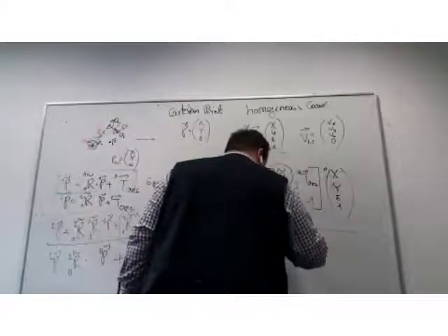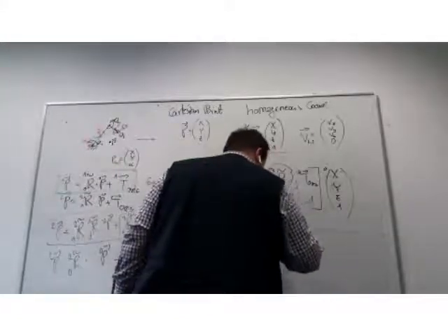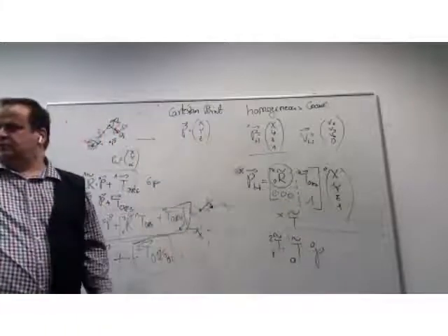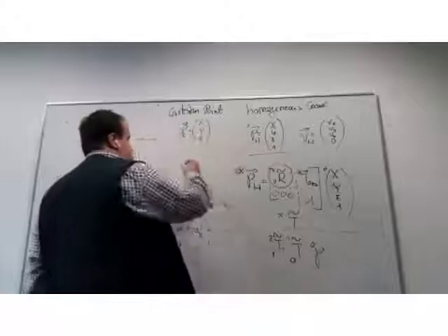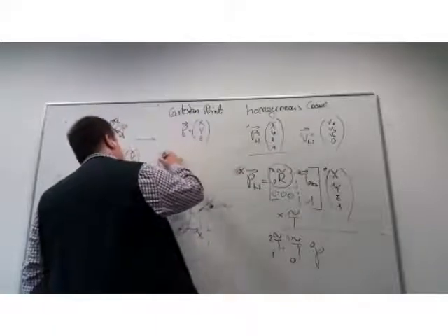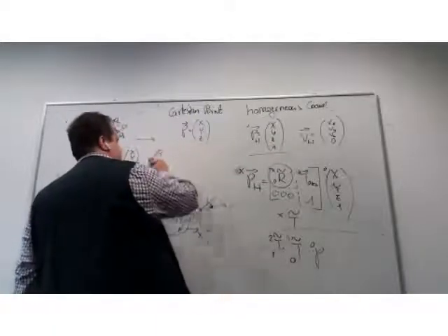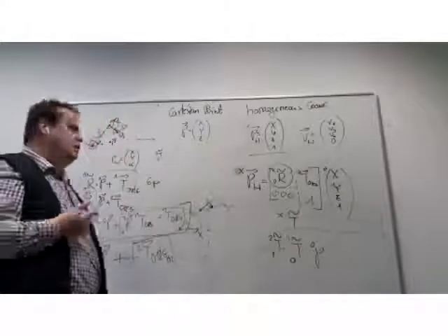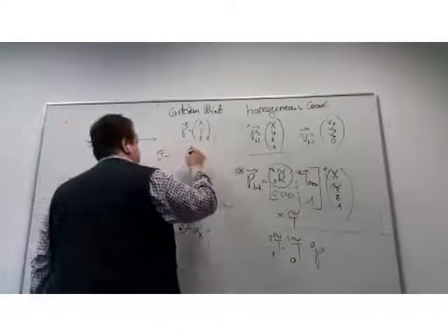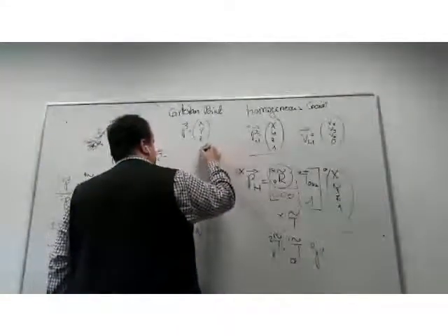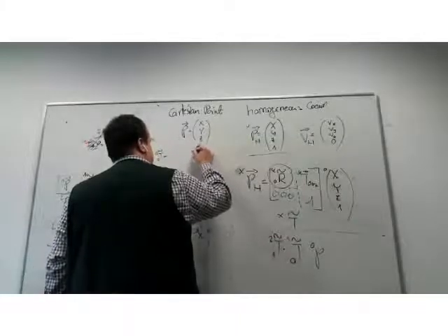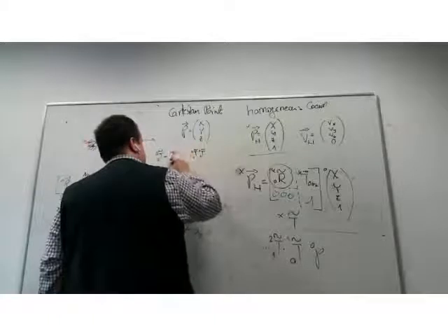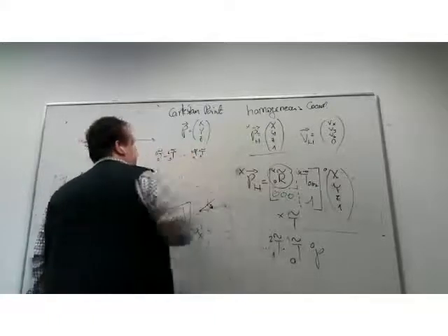I continue multiplying it with the matrix from 1 to 2, and so on. So to get the transformation from 0 to 6, if I have a 6-dimensional robot, we need to get 0, 1, 1, 2, all the way to 5, 6.